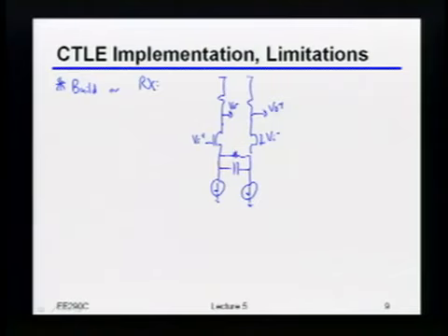At high frequencies, this capacitor kicks in and shorts the two sources together, which gives you higher gain at higher frequencies. Which, if you remember, we were trying to build a high-pass filter, or maybe even a band-pass filter. That's exactly what we were interested in here. Again, there are lots of ways to build these equalizers, but this is the most common one, or hopefully one you've seen a couple times before in 240.